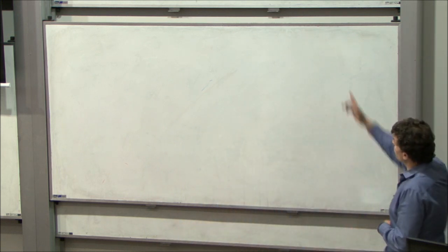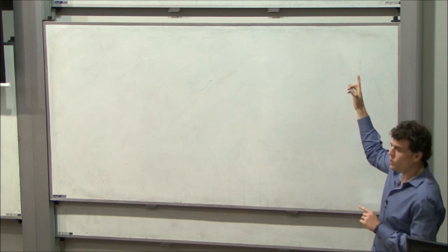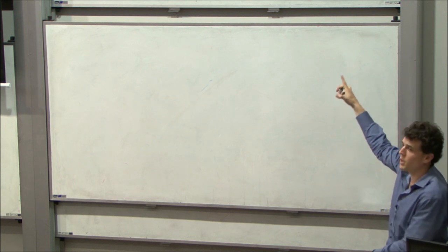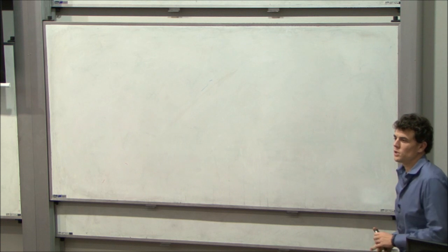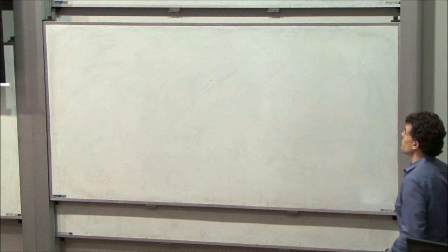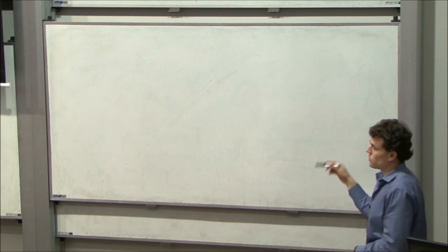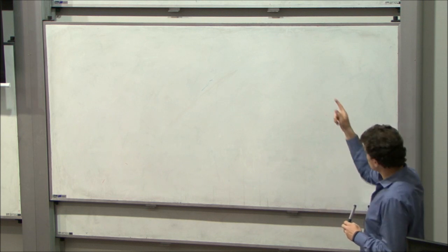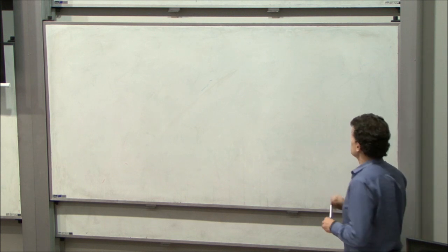So if we looked at our problem up here, if we started at 3, we could actually calculate the shear flow in panel 3.2, and we could calculate the shear flow in panel 6.5. But once we get to that junction at either 2 or 5, we run into a situation where we've got an unknown. We end up in a closed section. There's an unknown shear flow in our closed section. So what we have to do then is make a cut once we get to that stage and work out our qb, then we work out our qs0 and we can solve. The trick is that we just need to make sure that we get all of our equilibrium right once we get to those intersections.